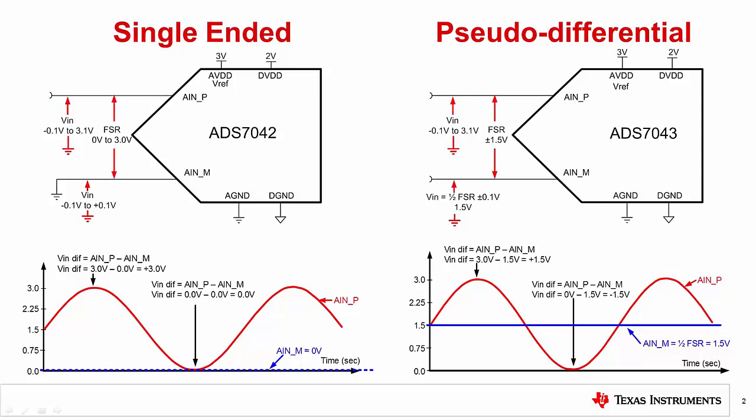Note that the ground sense has a very limited range. Typically, the ground sense can be at plus or minus 100 millivolts. The graph at the bottom shows how the input is calculated relative to the ground sense. So, if there is a small error signal on the ground pin, it will be corrected for.